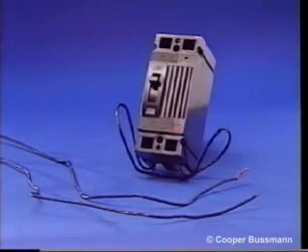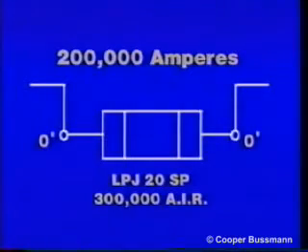It is important to recognize that faults can occur at the load terminals of the breakers. When this happens, the additional impedance of the test leads is removed, and the breaker may experience a fault beyond its originally tested value. This is the one-line diagram for the last test.